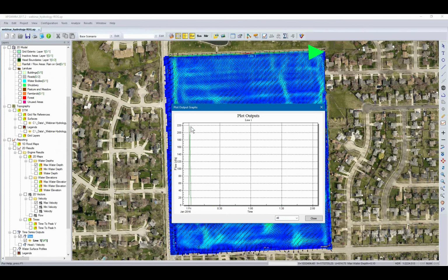Now, I didn't spend a lot of time calibrating my curve number analysis with my 2D analysis, so values may be off a bit, but we have that ability to look at not just flow to a single point or a single discharge like we do in a standard 1D catchment to node, but to look at rain over a terrain and capture it along a linear element.